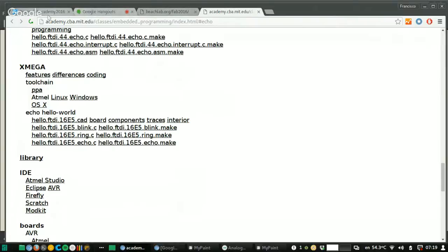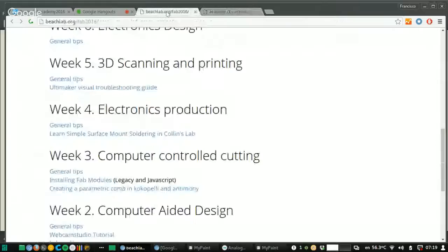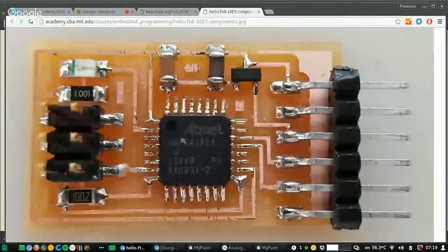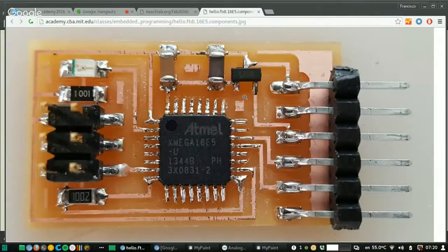The bootloader is a program you put in here, and you also set one of the fuses high, which allows it to self-program. So the next time you can enter the program through serial. But this program, the bootloader, is already taking some space of the microcontroller.